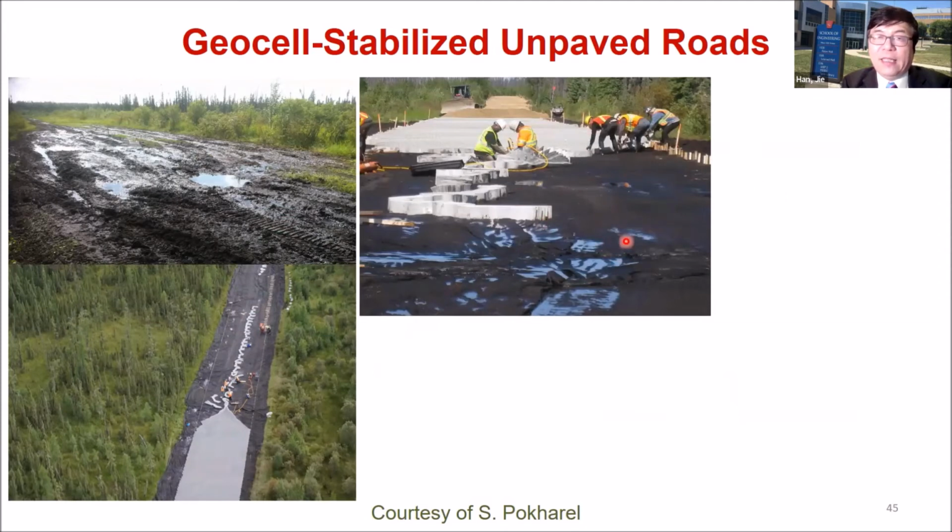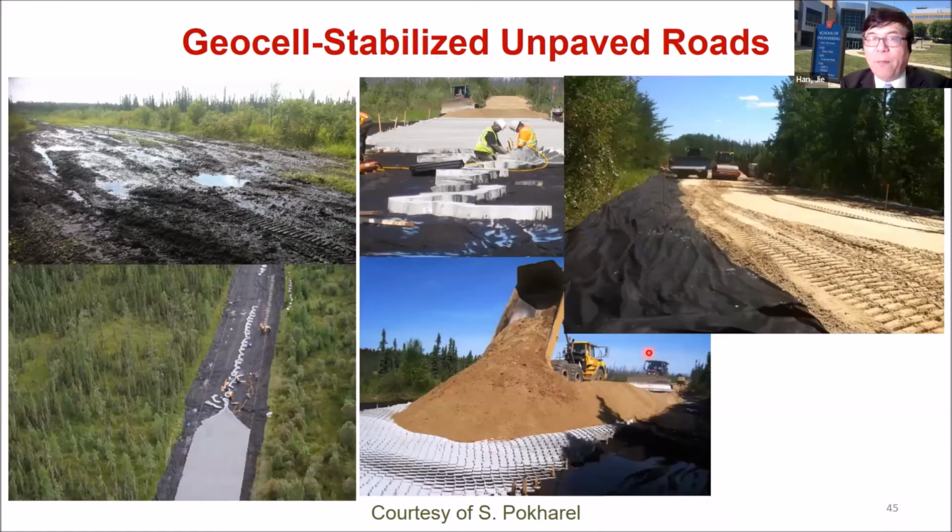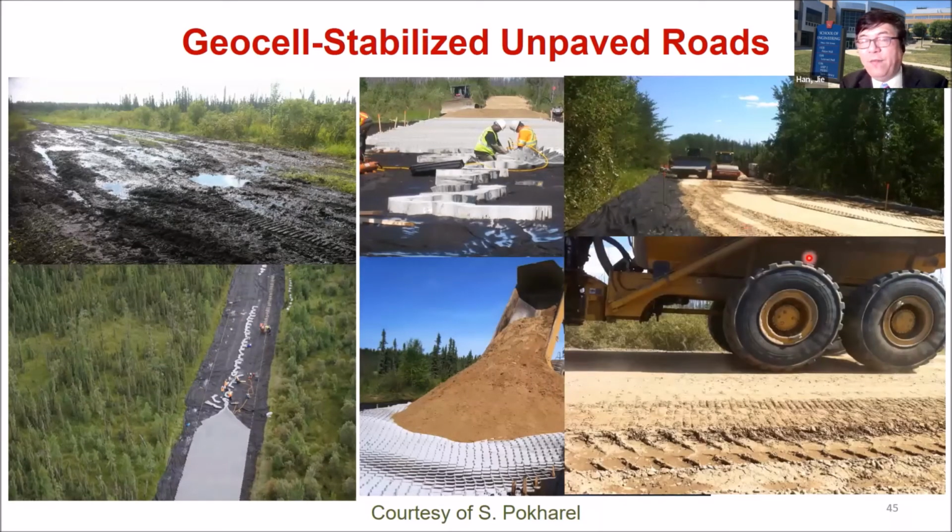And this is at the bottom, this is a geotextile as a separate. And then you can backfill the material, sand from on site. And this is basically doing the compaction, okay? And this is basically carrying very heavy vehicle on top of this very soft soil with geocell stabilization.